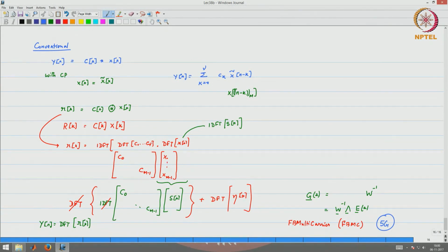But it turns out that result is something M channel perfect reconstruction filter banks have already solved. That is a known problem. What should those polyphase component matrices be? That is a known result. So again, we can just borrow that result from there. Okay, thank you.